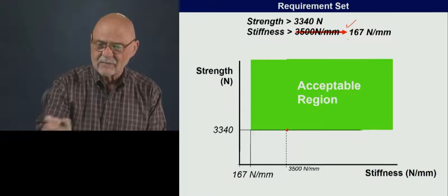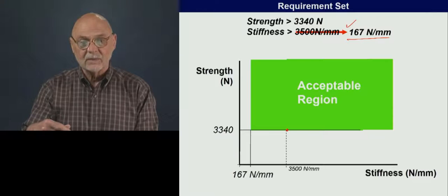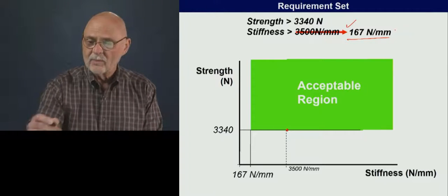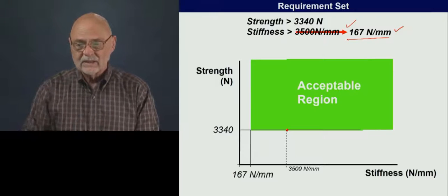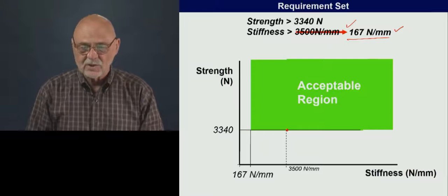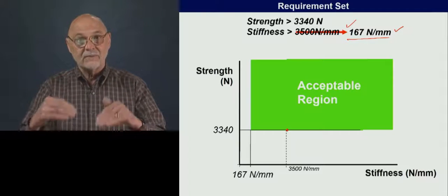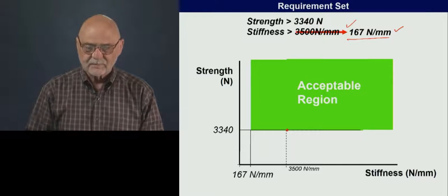If we pick a different kind of proportion between the strength and stiffness requirement, and this is more in line with what we might see in the requirement of a building, say an I-beam holding up the ceiling. Typically in civil engineering structures, they can deflect more than what we are looking for in an automobile.